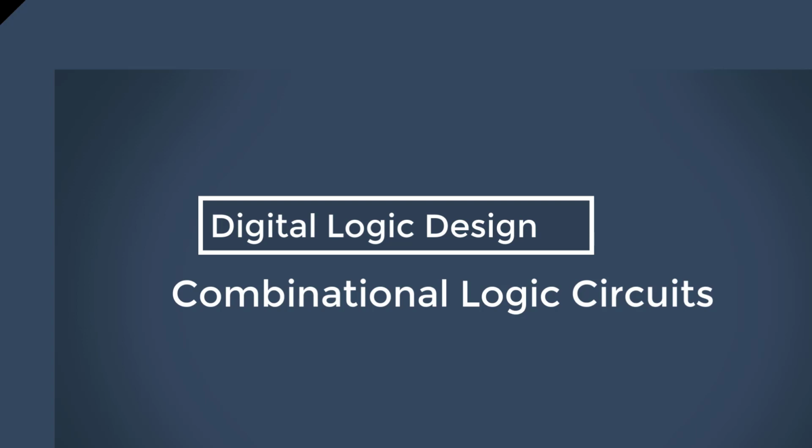So today I would like to give a lecture on combinational logic circuits. So what is a combinational logic circuit? It is that digital circuit whose output depends only upon the current inputs. So if there are any changes made to the current inputs, we see an immediate change in its output. That's a combinational logic circuit.